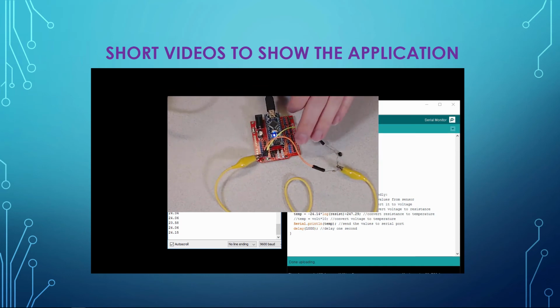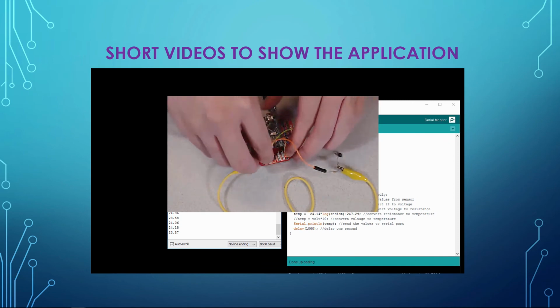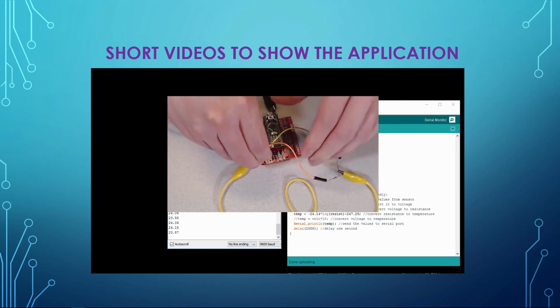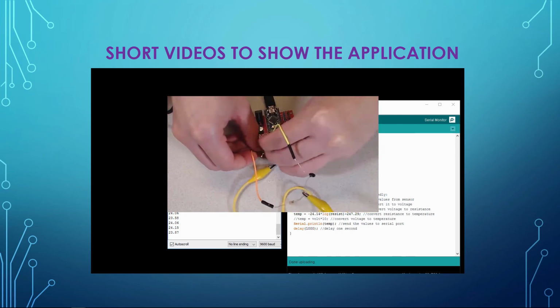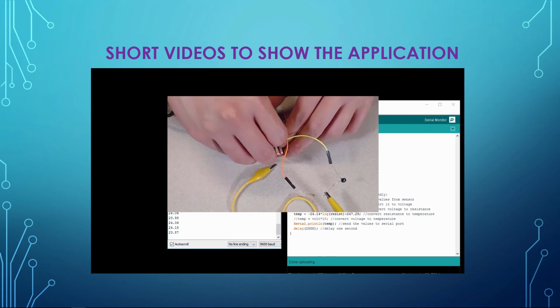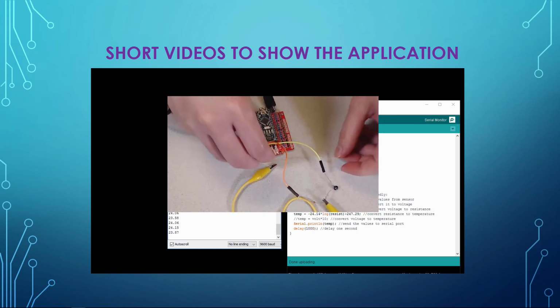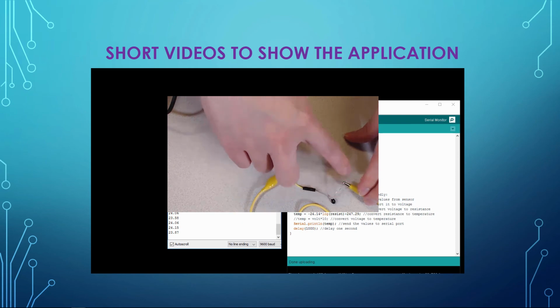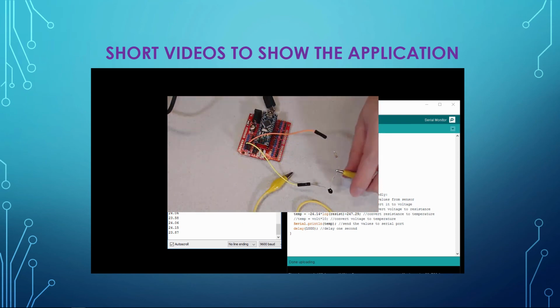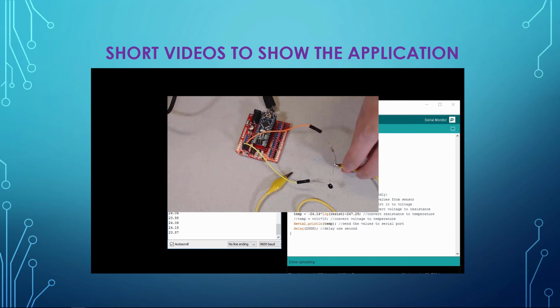So first of all, I'm going to disconnect the Arduino. And I need to swap these two pins here. Anybody knows why? So now the voltage divider circuit is reversed. So the current is going through the temperature sensor first and then into the resistor. Okay, so the reason we changed the orientation of the circuit is because now we want the output of this node here to go up when the temperature goes up. In the last circuit, it was the reverse. Anybody wonders why?